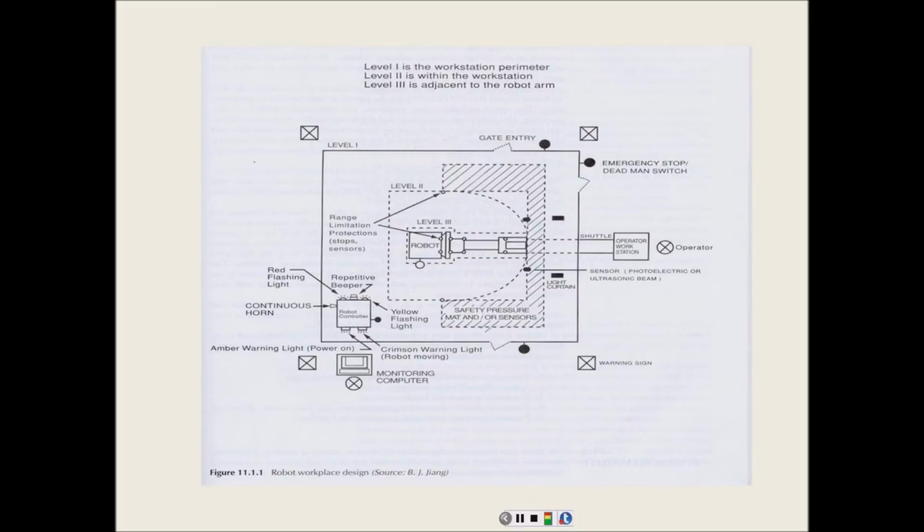By the way, I don't think this brings it up, but it's required that the robot controller be outside of the maximum space of the robot.